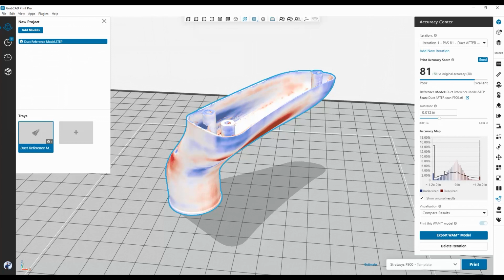Down here in the histogram, you can see the number of triangles that are deviating from the center point is a lot smaller, and it's a bell curve, which is what you want. What it's basically doing is removing the outliers on the side. You can see the old version in the black line here. Okay, and then you can export this as well if you want to take it somewhere else.